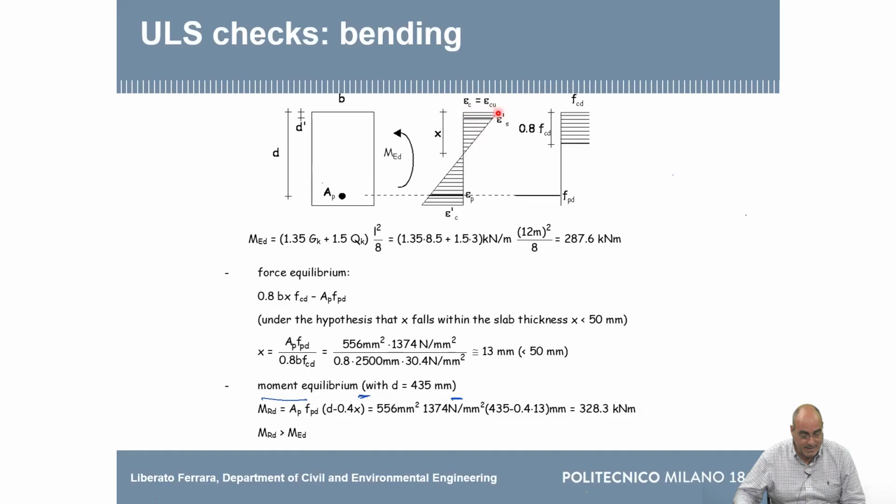And you see we have compressive strains in the concrete. Then we have tensile strains here, whatever they mean. And we have put, as a symbol, all the area of the pre-stressing at one point, in the centroid of the pre-stress. At that level, because of the perfect bond, we know that the strain that we read on the concrete strain diagram is also the steel strain. So in this diagram there are already two of the assumptions of the reinforced concrete theory: planar cross-section plus perfect bond.